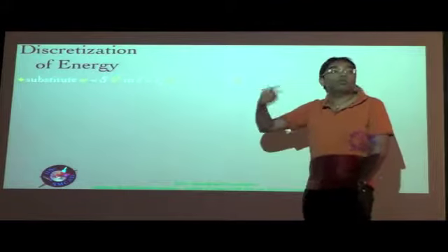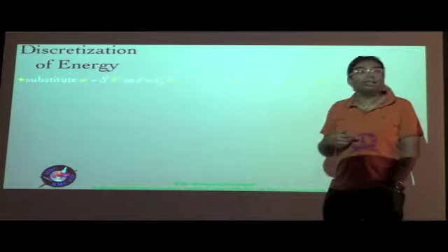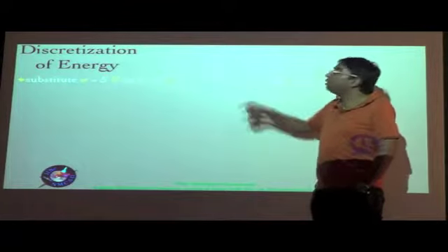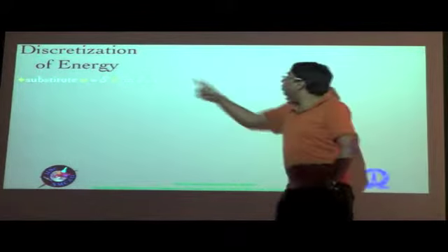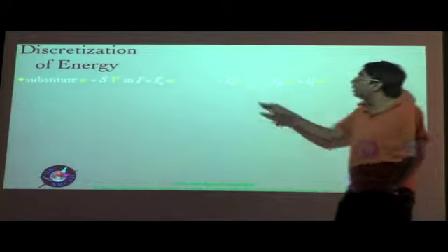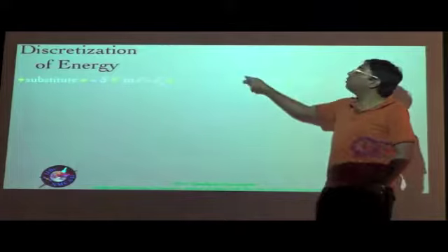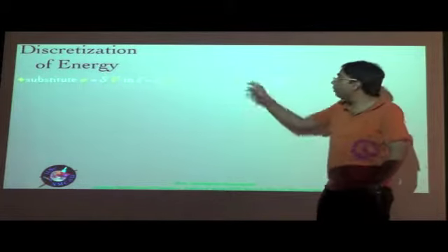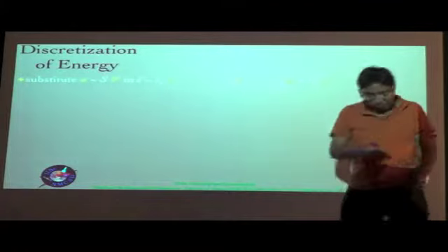That is something we will force upon this method later. So we know that it has only 4 degrees of freedom, and those 4 degrees of freedom are contained in this, and those warpings in turn, when we solve for it by minimizing the strain energy per unit length, we would see become functions of that epsilon bar, and basically the entire strain energy is a function of that epsilon bar, which is what leads to the 1D constitutive law.